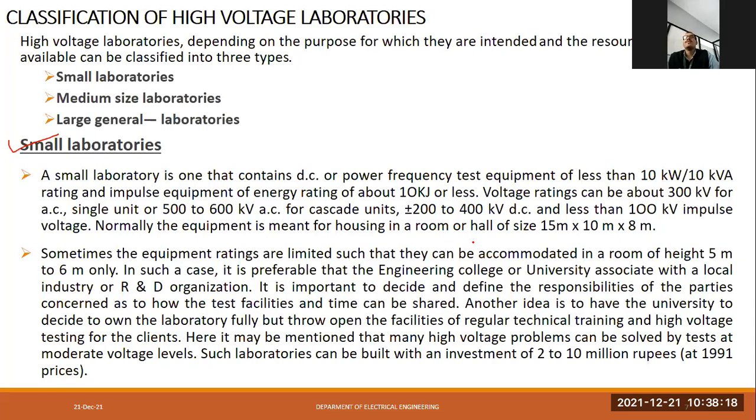Here, whatever power frequency test equipment there is, its rating should be less than 10 kilowatt, or we can say 10 kVA rating, and whatever the impulse equipment energy rating is, that should be 10 kilojoule or below.